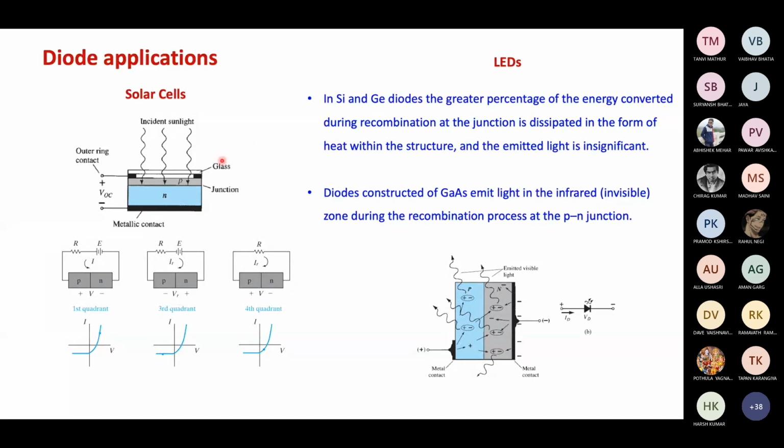as well. In the first quadrant of this, the voltage is positive, the current is positive, and it means that the total power is positive and the power is being taken by the circuit. The power is dissipating. If you know the convention, if the net power is positive in a circuit, it means that it is consuming the power.